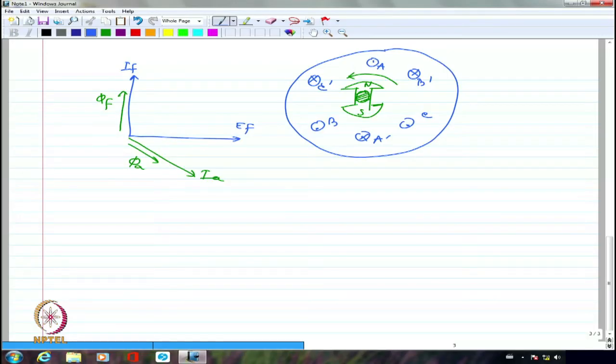One portion I am showing as EF, which confines itself only to the rotor flux. Another portion I am showing as XAR or XM, which is the induced EMF due to the armature currents, which I call armature reaction or armature flux based induced EMF.